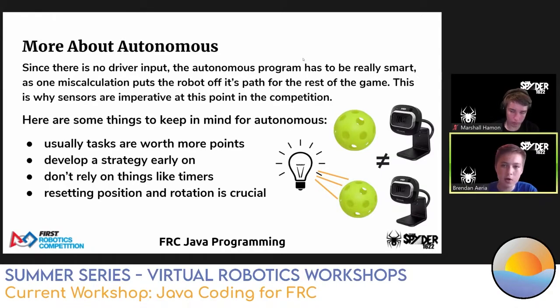So now we're setting the robot's position. No matter how flawless and reliable your autonomous code is, there might always be a chance for something to go wrong and put it off its path. And when this happens, it's important to reset the robot to a reliable position and rotation. So whether it be banging the robot against the wall to line it straight up, or using color sensors to know exactly where the robot is, you always want to reset the robot throughout autonomous to make sure that it doesn't go all the way off course for that entire rest of the period. And I think this makes all the difference.